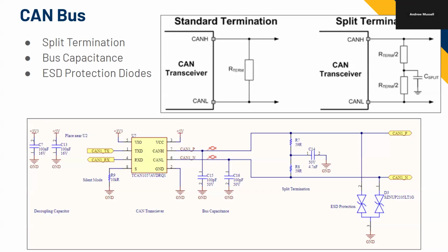So basically, if the voltage on your CAN1P line got too high, it would just shove that all to ground. Now, what voltage do we actually do that at? These ESD diodes are set to 24 volts, so that if your low voltage bus got connected to your CAN bus, it would shove all that power into ground and trip the overcurrent fault of your low voltage bus.